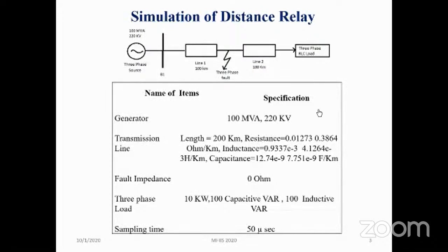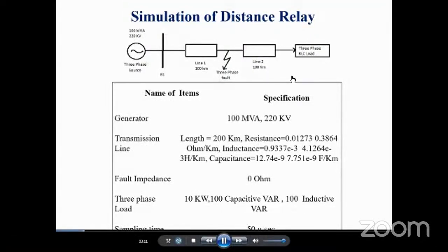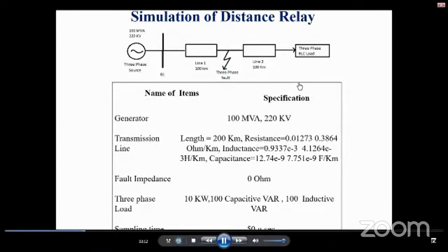The fault resistance or impedance has been kept fixed at 0 ohm. The other specifications of the system are given over here, with the sampling time being 50 microseconds, and the fault inception angle has been taken to be 0 degree.